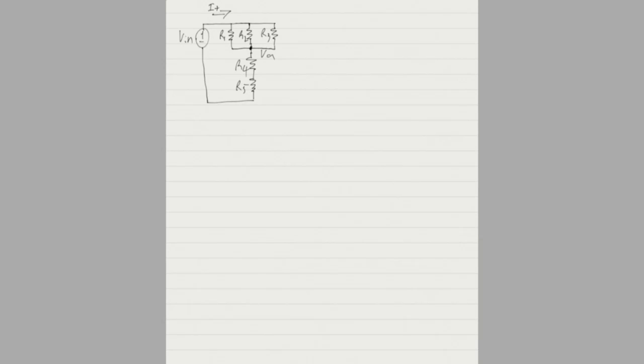There are 2 things that I want you guys to figure out with this. First of all, how do you do R1 parallel R2 parallel R3? What I'm going to say is parallels as an operation are associative. Look up the associative property. Remember what that is. It'll make life a lot easier. So that way you can combine these, and you can do that in whatever order you like. Just look up what I mean and look back at what I said about doing resistor chains in parallel of more than 3.